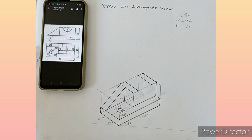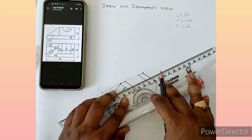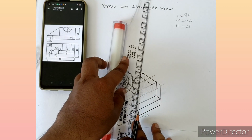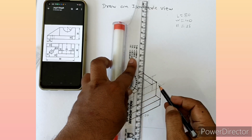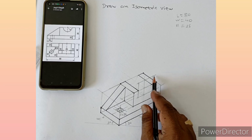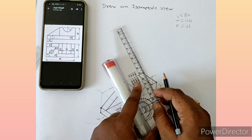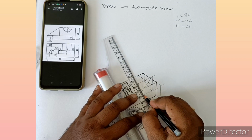Okay, now you have to make the parallel line. Okay students, so this is a 25 mm, this is also a 25 mm. Okay, now students, what you have to do, longest diagonal you have to join. Okay, you have to draw two lines which will intersect this longest diagonal.